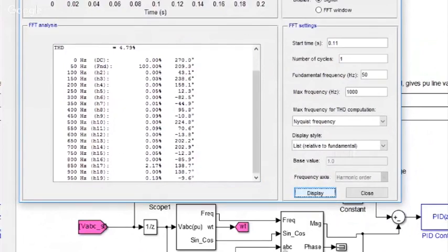So you can see that 17th harmonics is 2.17. We did not eliminate the 17th harmonics because selectively we choose. That's why that 2.17 is contributing to that 4 point something. Okay. So according to our aim, the deadliest harmonics we eliminated and we brought it down. So individual harmonics also you can analyze like this.